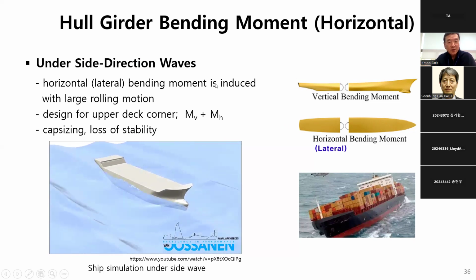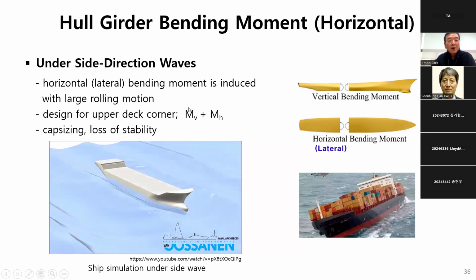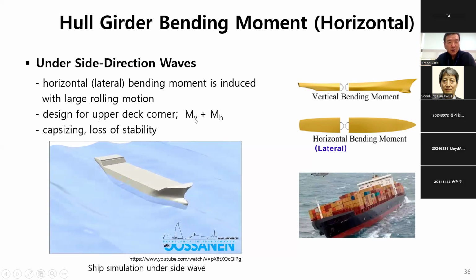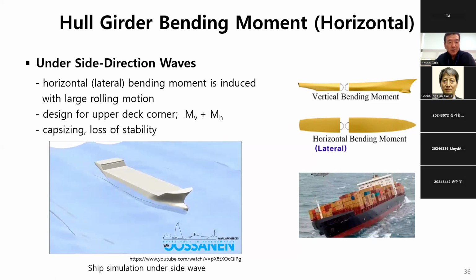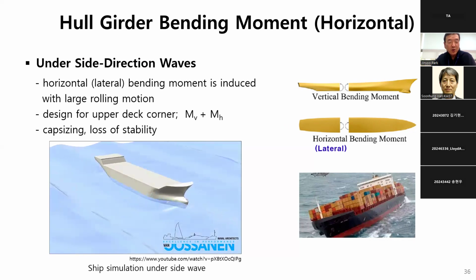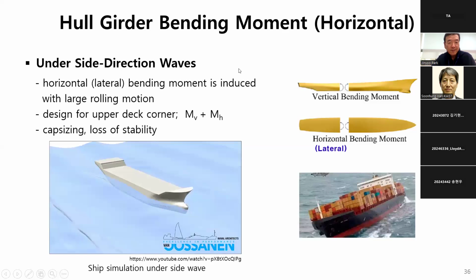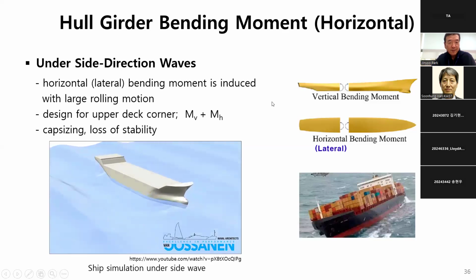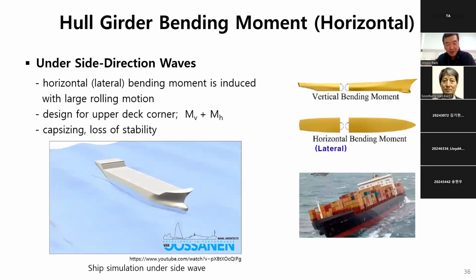This horizontal bending moment is sometimes coupled with vertical bending moment, inducing the maximum stress at the corner of the deck. Sometimes it causes the ship to capsize and the loss of hull stability.